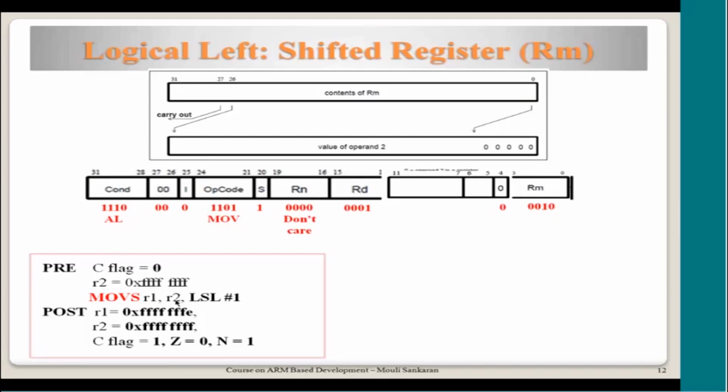Now you see here it is a single operand instruction, so it was filled with 0, but it won't interpret it as a valid value, and then it knows that R2 is the second operand, so it has filled 0010 here. Now it has to interpret this. You have mentioned that it is a logical shift left. So if you remember previously, for LSL these 2 bits happen to be 00 if it is a logical shift left. So it has filled promptly a 00 value, and then it is left with only filling this constant. It is given as 1, so it has filled 1.